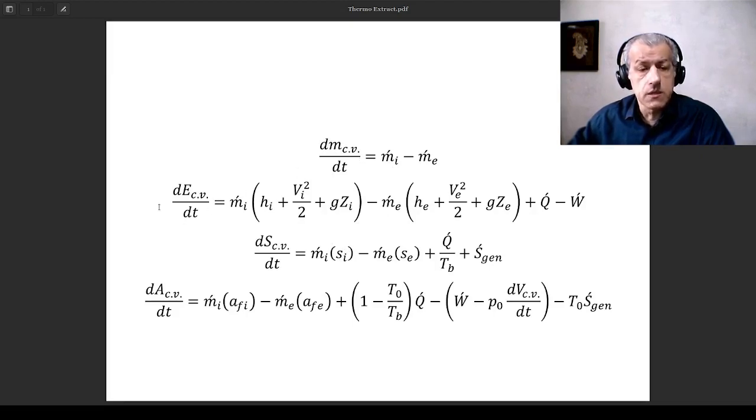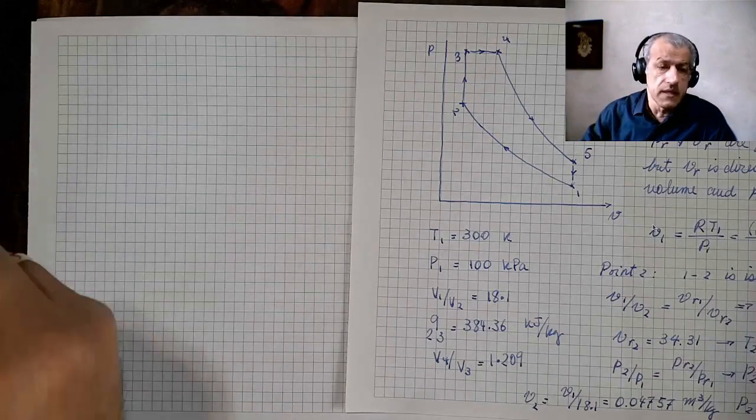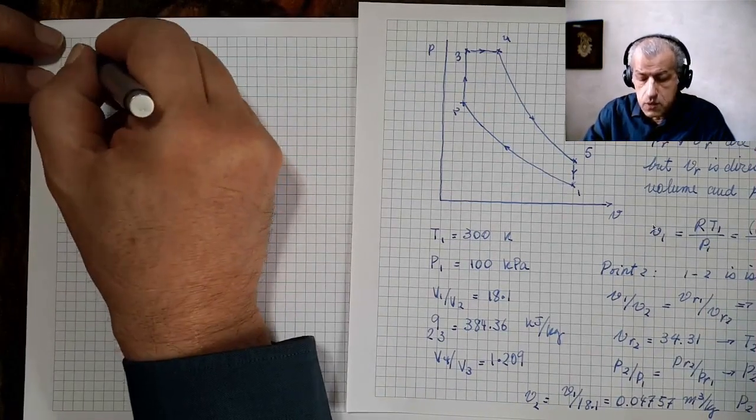Here, there is only the change of energy, which equals heat transfer and work, whichever is available in that process. And for process 1, 2, there is no heat transfer. It's an ideal, reversible process for the ideal cycle. These two terms also vanish since there's no mass entering or leaving, so the initial and final entropies are the same.